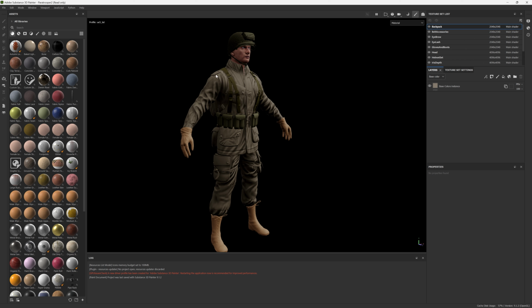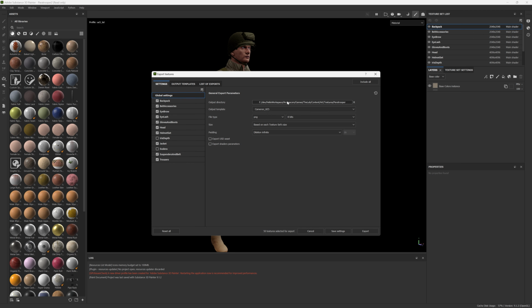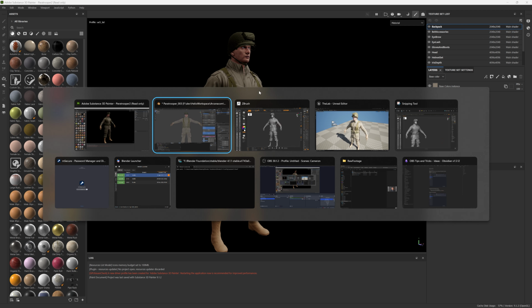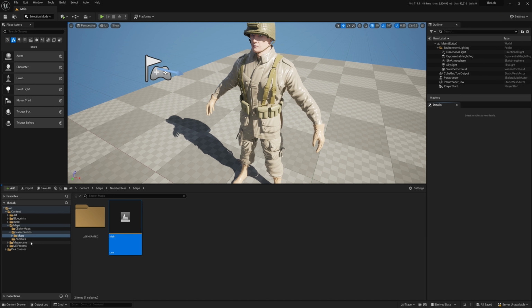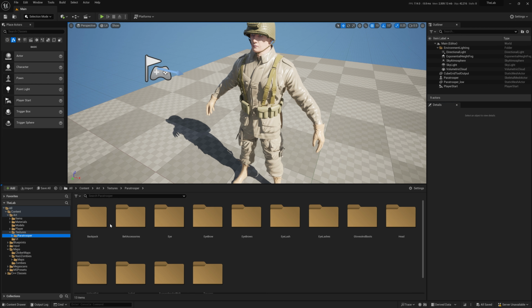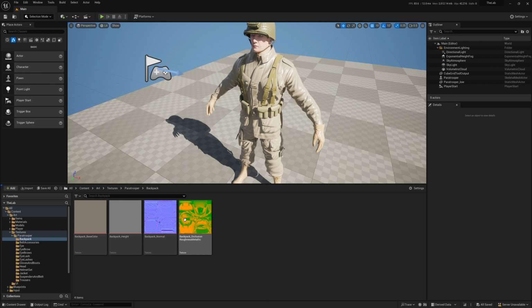So when I go and work on these textures, they automatically generate. If we go up to File, Export Textures, they're going into the texture area in my Unreal content. So when I come in here, get out of this, and go into my textures area, it's automatically generating all those maps. And then I just refresh in here. So the idea here is iterate, iterate, iterate. And again, I'm gonna go into all kinds of detail on the importance of iterating because it's just super key.